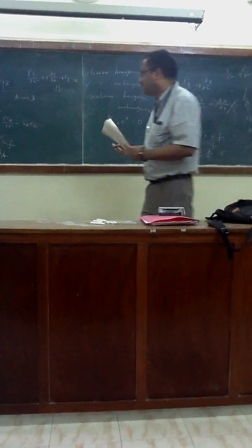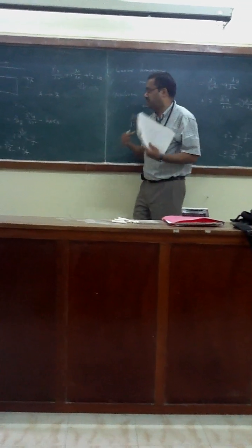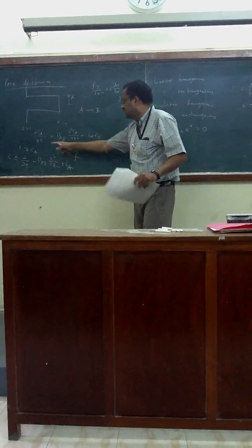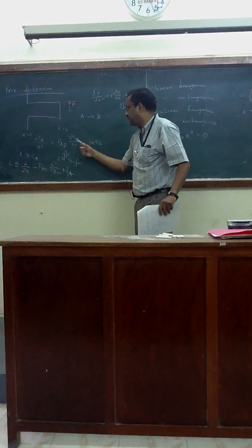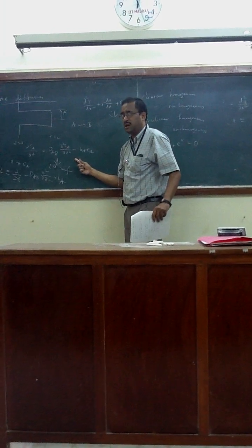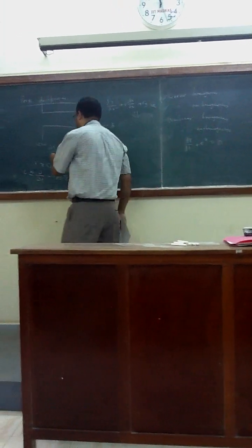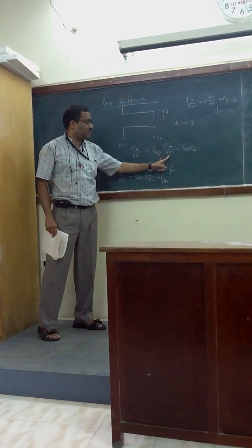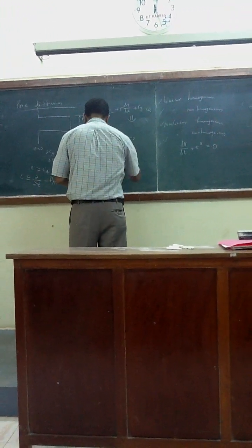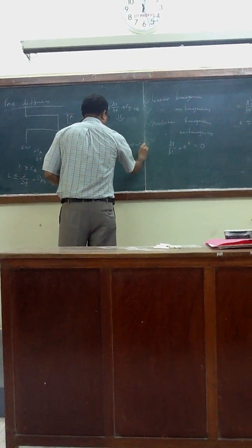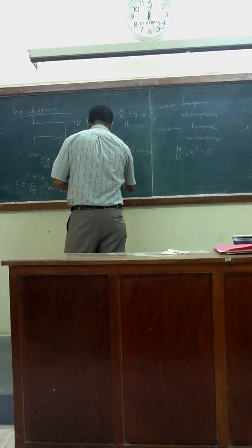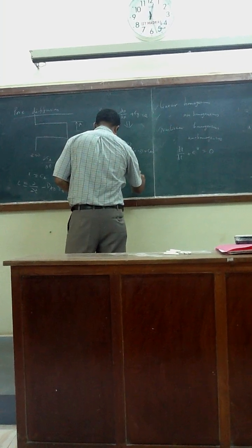Okay. So now we have seen how the operator is actually coming. You can see this operator format. Any chemical engineering problem you can write down. That's one beautiful thing. But this has a time derivative, first order, and a second derivative in space. So we need to have one condition for time and two conditions for space. This time condition is called the initial condition and these conditions are called boundary conditions. Okay? So at z equal to 0, one can have Ca at z equal to 0 is Ca0, and at z equals L, this point, you can have minus D_AB dCa/dz equals K Ca.